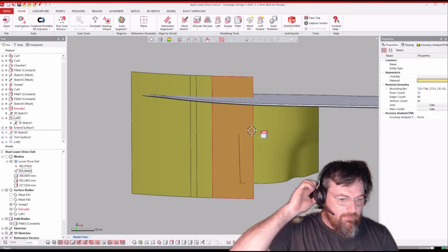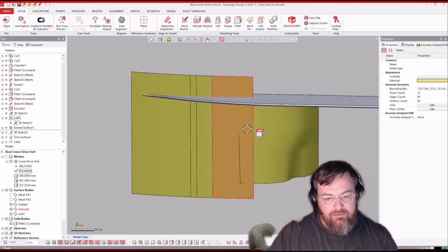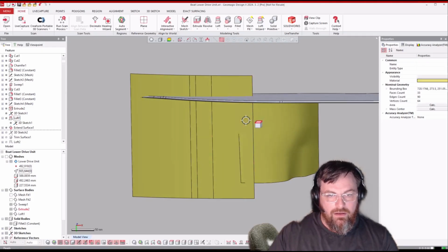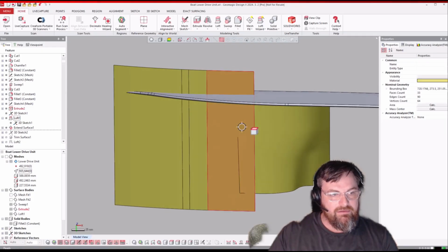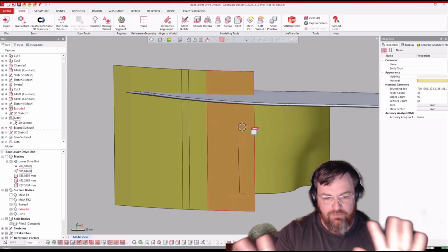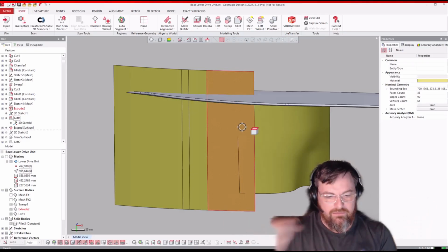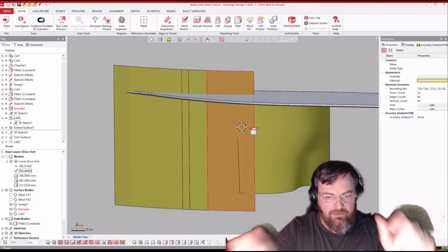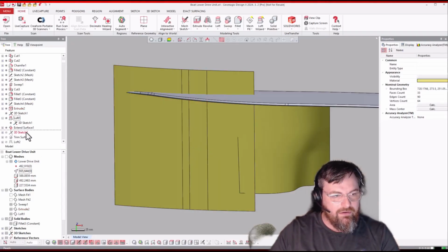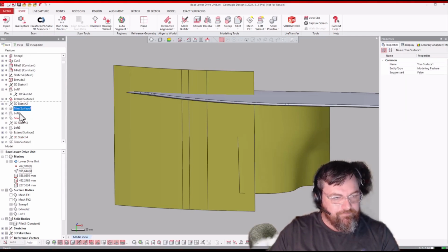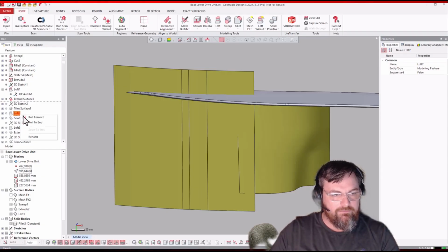The way we go about modeling in here sometimes is we go ahead and fit a bunch of surfaces, then trim them back and loft them together and stitch them, and that's going to be that same sort of workflow here, where we go ahead and rough in the pieces that we're going to drape. Think about upholstering it with CAD surfaces, right? We're going to drape a surface over it, and then we're going to cut the shape of the outside of it, and then we're going to stitch it together with the surrounding areas. I know I use that analogy often, but CAD surfacing is very similar to upholstery in a lot of different ways.